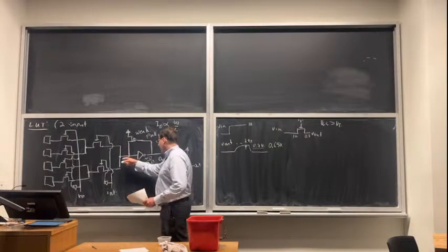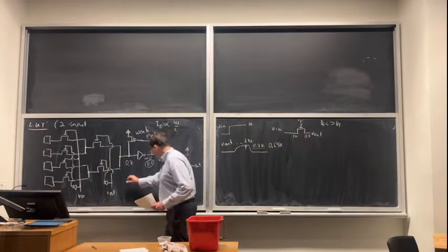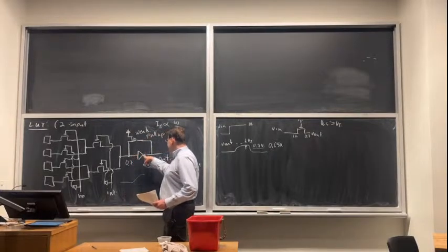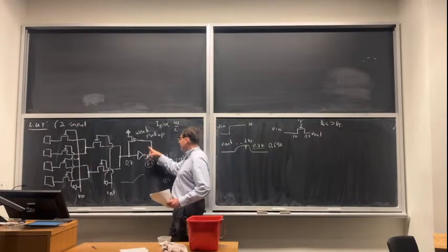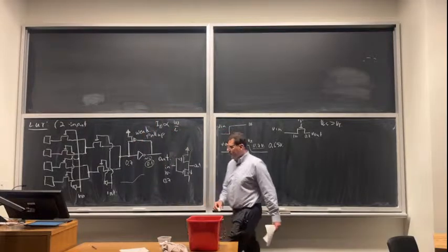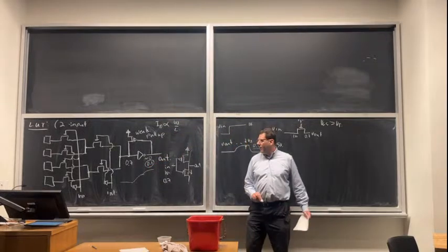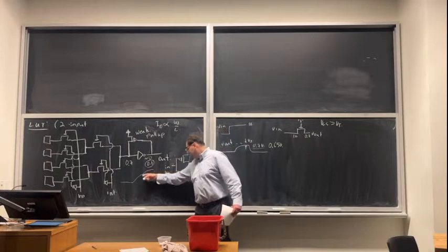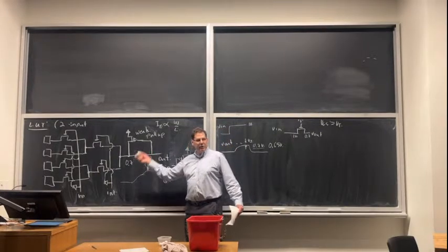So what happens is, when the signal is rising to 0.7 volts, it gets to 0.7, this output is nearly 0, because this is an amplifier. This turns on, and it pulls it the rest of the way up. So it'll keep going and go all the way to logic 1. The downstream logic has already been passed pretty much as 0, so this last part doesn't really cost you much delay, but it guarantees that you're not leaking current like crazy.